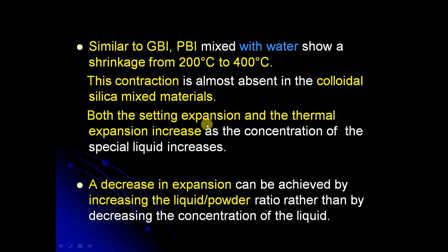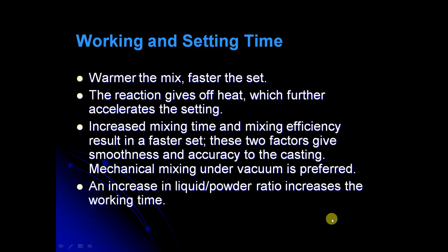Both the setting expansion and the thermal expansion increase as the concentration of the special liquid increases, because in the phosphate we are using the aqueous colloidal solution rather than water. A decrease in the expansion can be achieved by increasing the liquid powder ratio rather than by decreasing the concentration of the liquid.